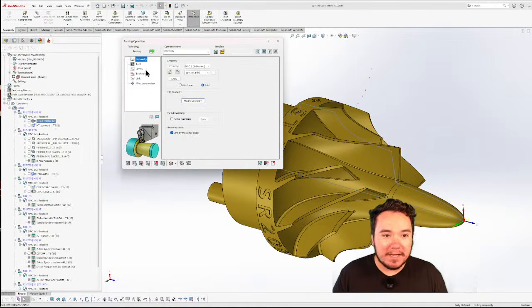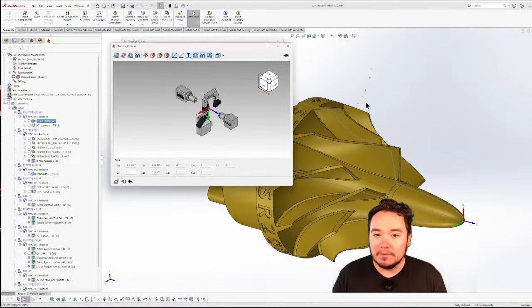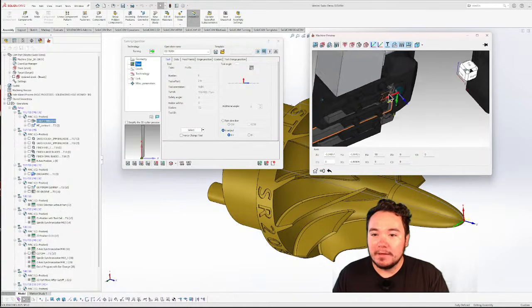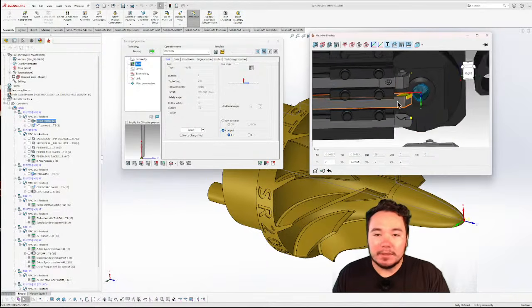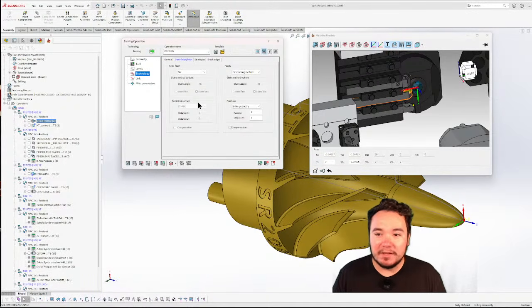That's pretty much that. Selected my tool, and you can see the tool here in the machine. Got everything modeled in. Awesome. And then from there I can select if I'm going to do a finish only, if I'm going to do a rough. So this is straight to finish. Since we're working on a Swiss machine, it's got that rigidity because that guide bushing's there.